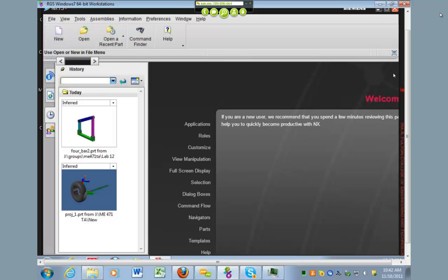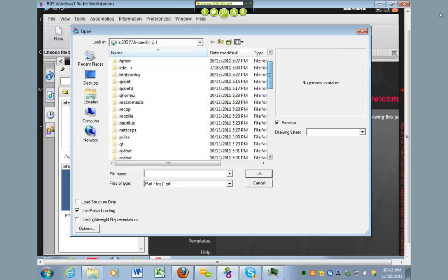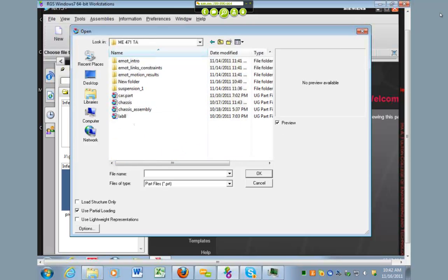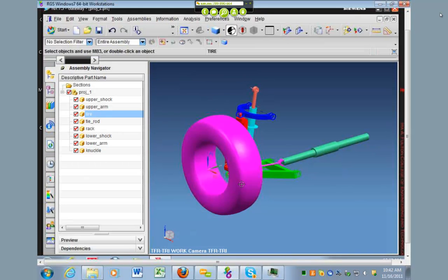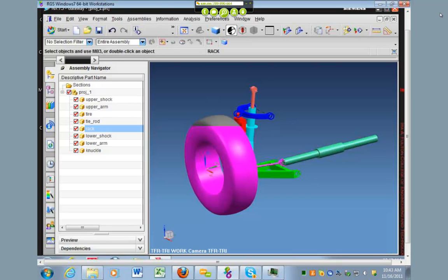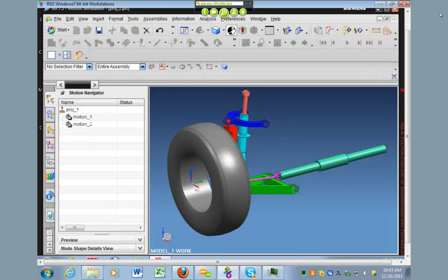So it mentions there are two joints, J007 and J008, which are both drivers, and so we'll be using those. The J007, in the picture on page 4, moves the suspension up and down, moves everything up and down, and the other one pushes this in and out to turn the wheel. All right, so let's go to motion simulation, and let's hope this works.